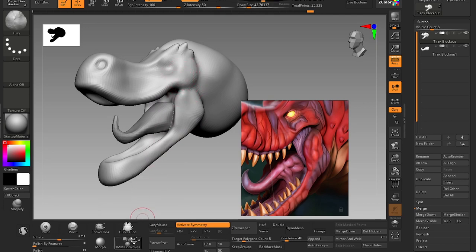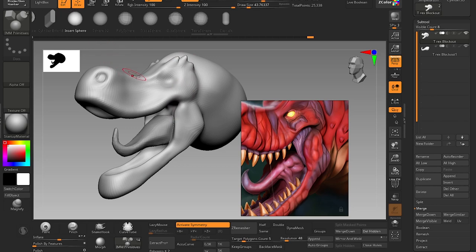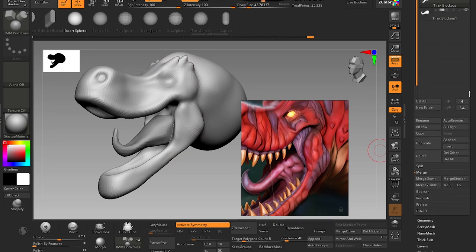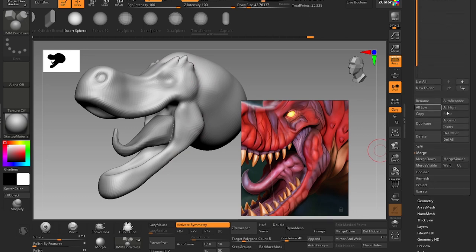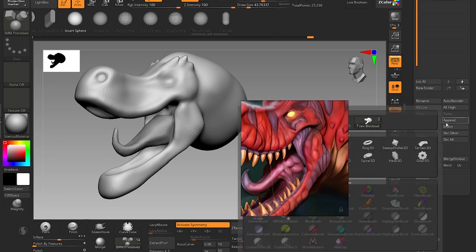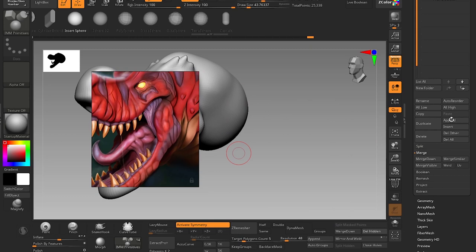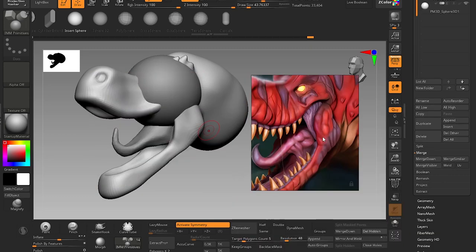It doesn't work, because if you choose a primitive brush and choose any of the subtools and click and drag, it will say that this mesh of yours has subdivision levels on. So what I will do is append. We can go and append it here by clicking it, append, and I will choose a sphere. I will move it aside.